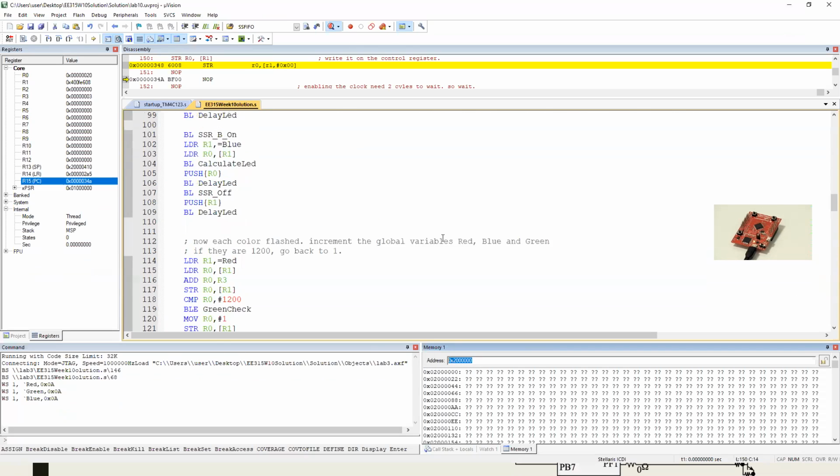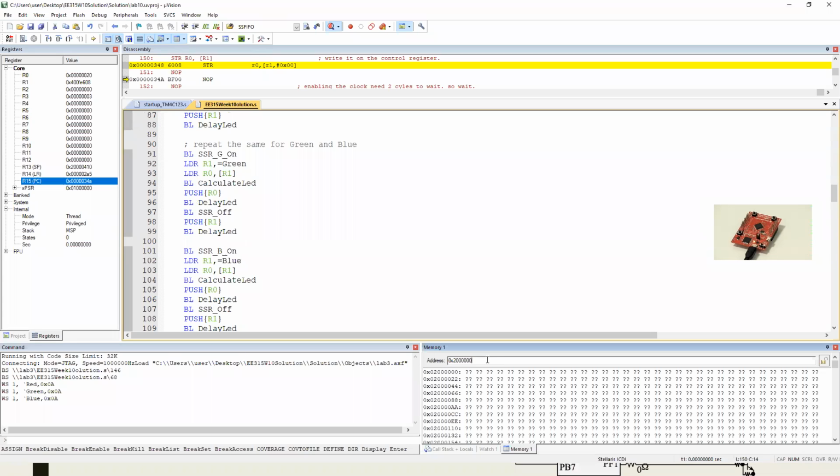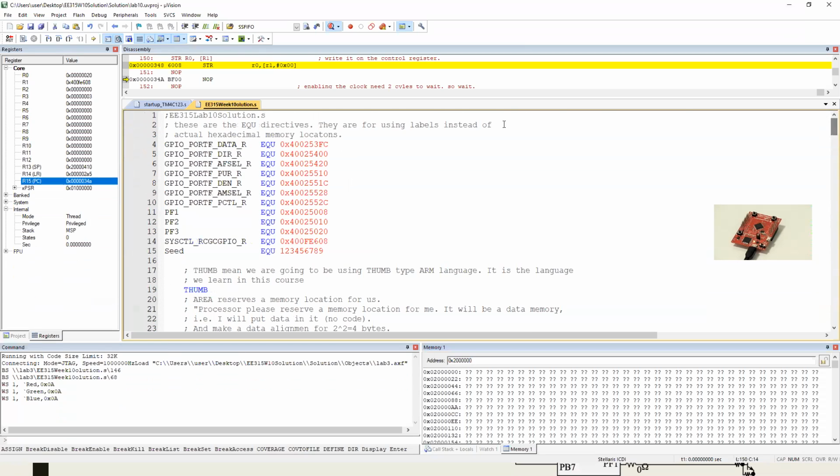So guys, I'm going to ask you a question. We could observe the memory, right? Anytime we want. Let's try to observe this address. We'll be able to observe it? Yes. It's just like a memory address. As you can see, you're observing the memory. However, it is not the memory. Because this address is mapped to that register, actually the compiler, this interface, thinks that you are looking at part of the memory, but you know that this is mapped to that control register.